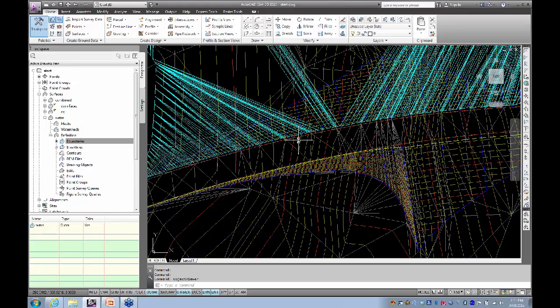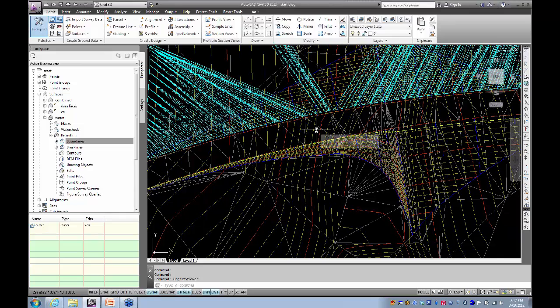Let's go and have a look at one of these faces. So I'd like to cut a spillway into this portion of the dam right in the middle of the screen here at the moment. The way I'm going to do that is actually not to use the grading tools at all. You could if you wanted to, and realistically it would probably do a better job, but I'm just going to do it this way to show that you don't always have to use the grading tools. And I'm simply going to do it by making the surface by break line.